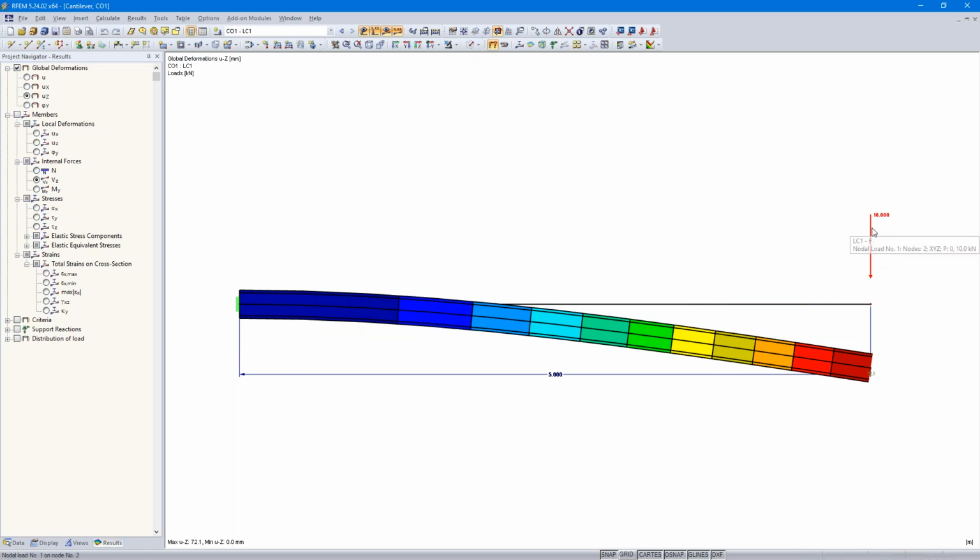And you can imagine if the load vector is on this point of the deformed structure, the angle between the load vector and the beam is not 90 degrees. And that's why there is a small normal force, and also the shear force is not exactly 10 in this case. I think with this deformed structure here, you can imagine what's the reason for such internal forces that you wouldn't expect.